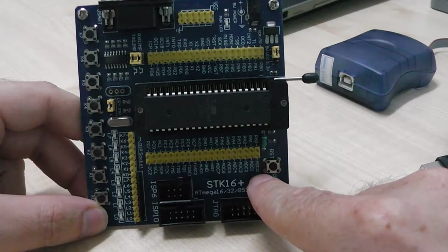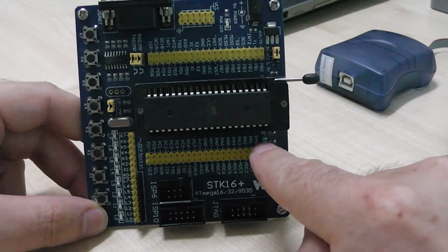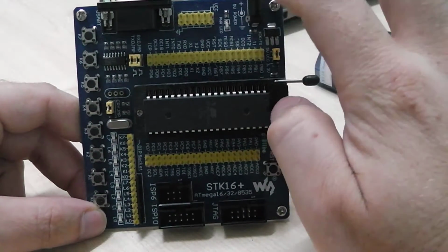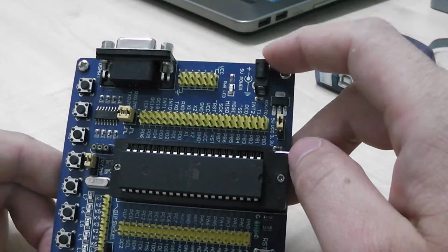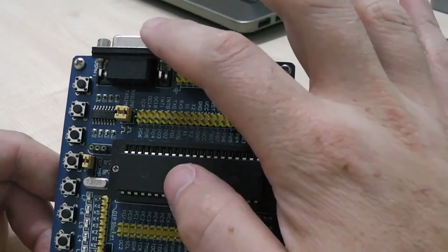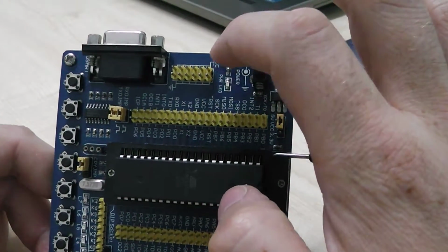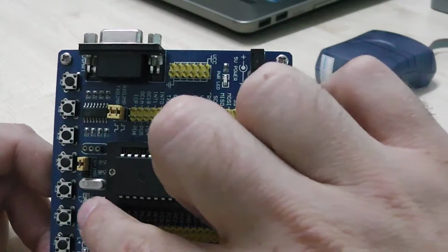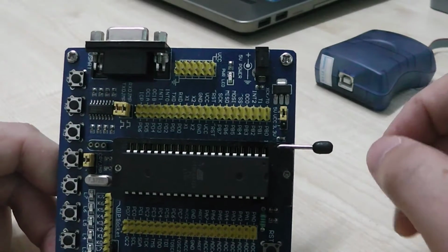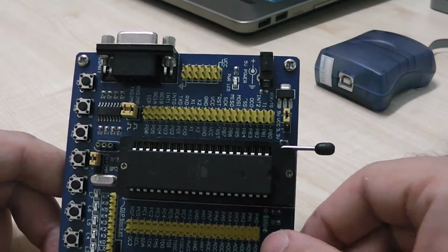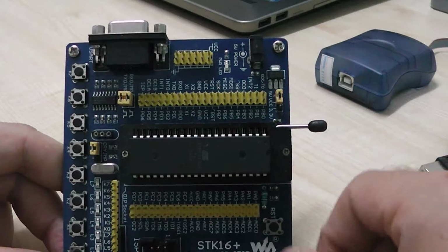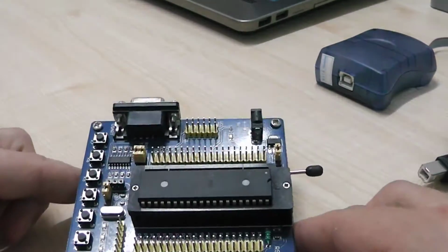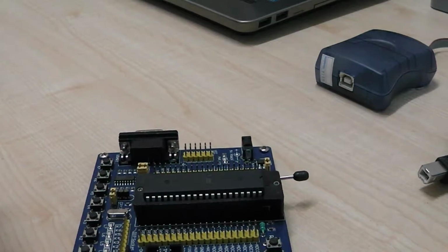As you see here, this is PA0, and it's the same as pin number 1. We have here the jack for the power, and for the serial we have 5 volts, VCC and ground, and we have the crystal, which gives the pulses, the clock. And we have a reset button, so in case you need to reset your program, you push the reset button. This is just a training board to facilitate using our microcontroller.